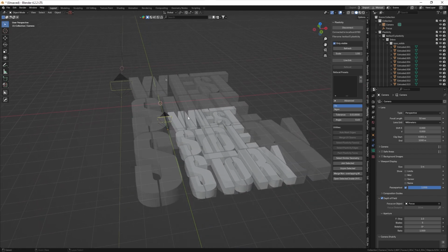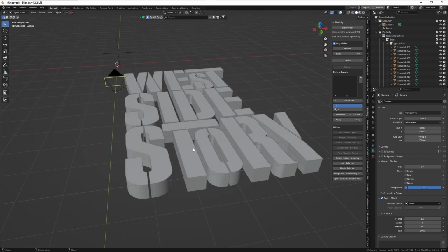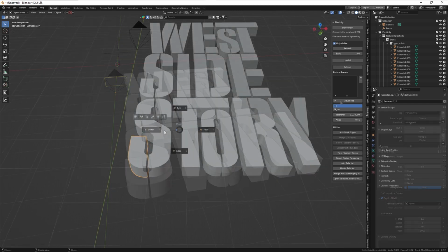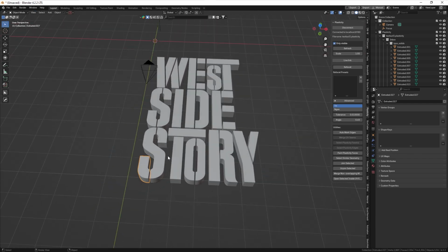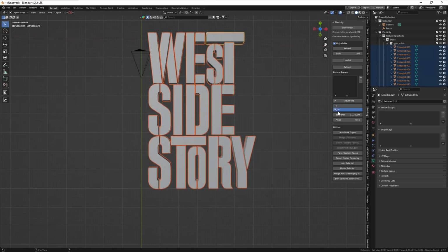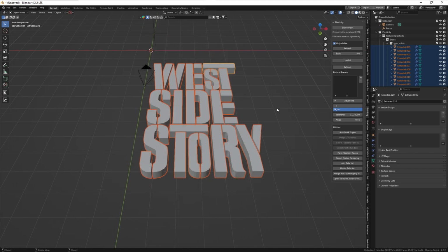Please ignore this. So what's important is, before doing anything else, go into face mode. You will see that our geo consists of tris, but we want these ones to be ngons. So therefore, let's select all these guys and go to ngon and refacet, while the auto mark edges is activated. So let's see if we were successful.